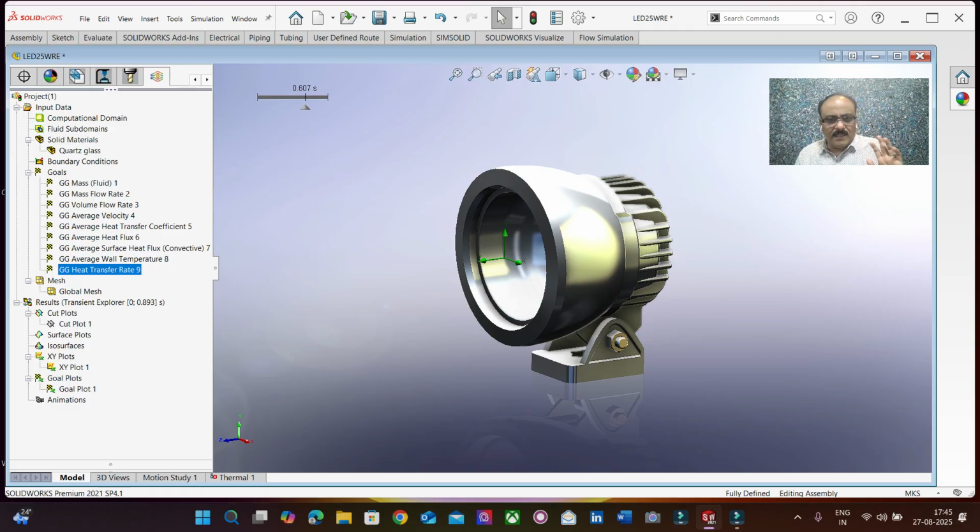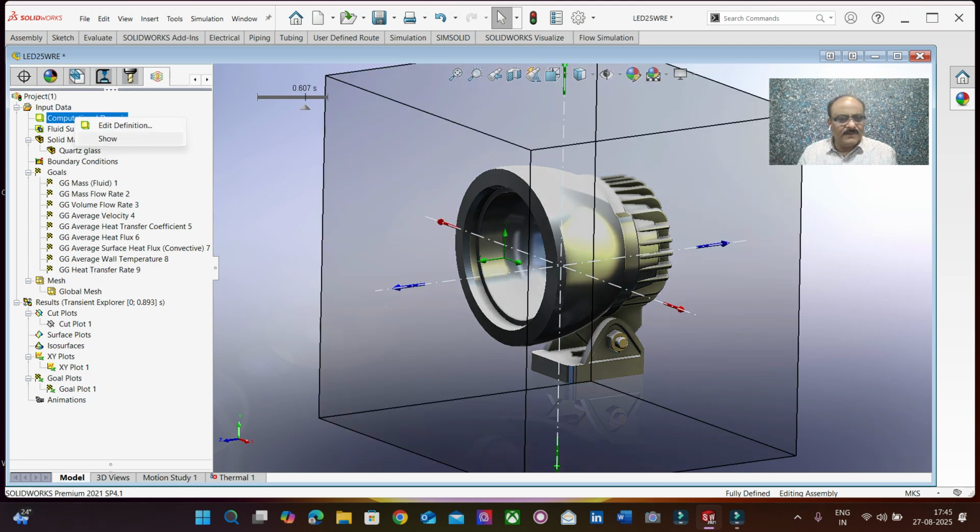Now I'm going to define the process. The process is going to be a finite volume system. We are going to break the entire computational domain, this is the computational domain, into individual cells, and I am going to define either cuboid or rectangular kinds of cells. Each cell can be the same size, or the cells can vary also.